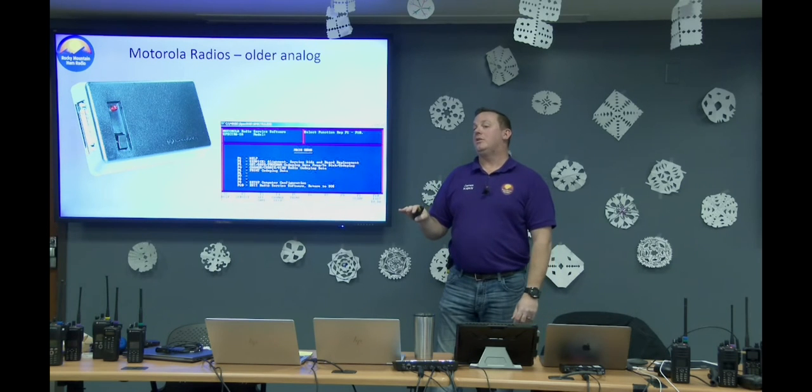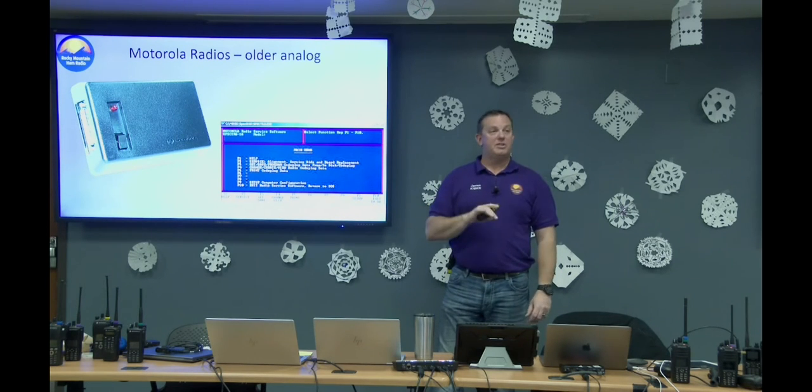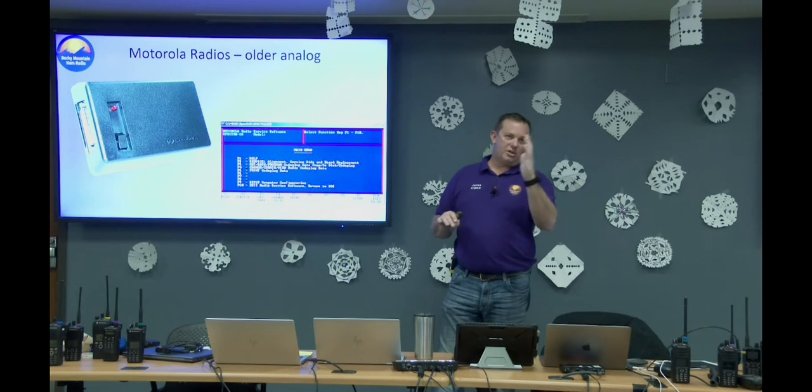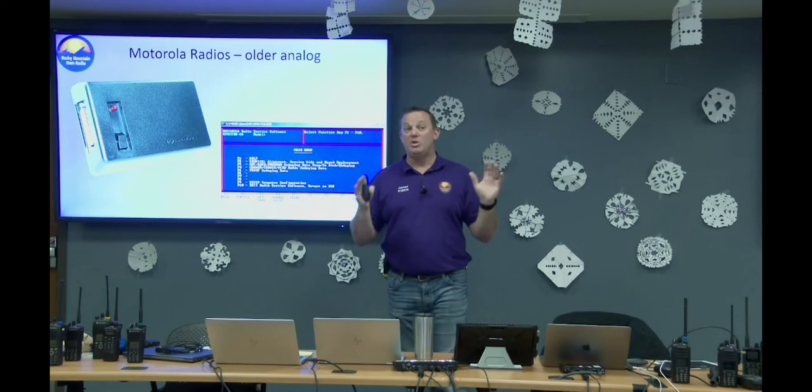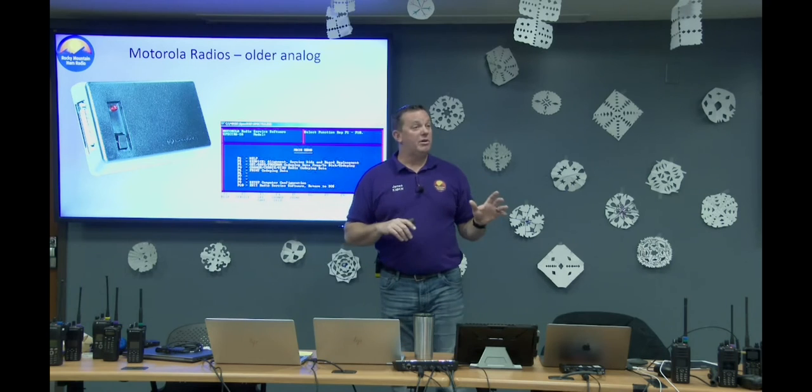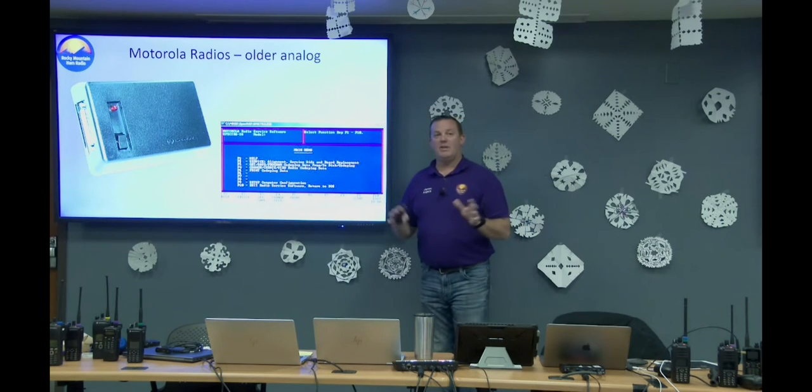Does that guarantee the radio is going to operate properly in that? It does not. Honestly, most of these radios are so close. What you're going to find is that they don't produce harmonics and birdies, but the PA becomes a little bit out of band. So you usually lose a little power. That's usually the biggest thing. If you want to do it right and be a good neighbor to everybody, you should have the radio checked on an analyzer after you've programmed it.